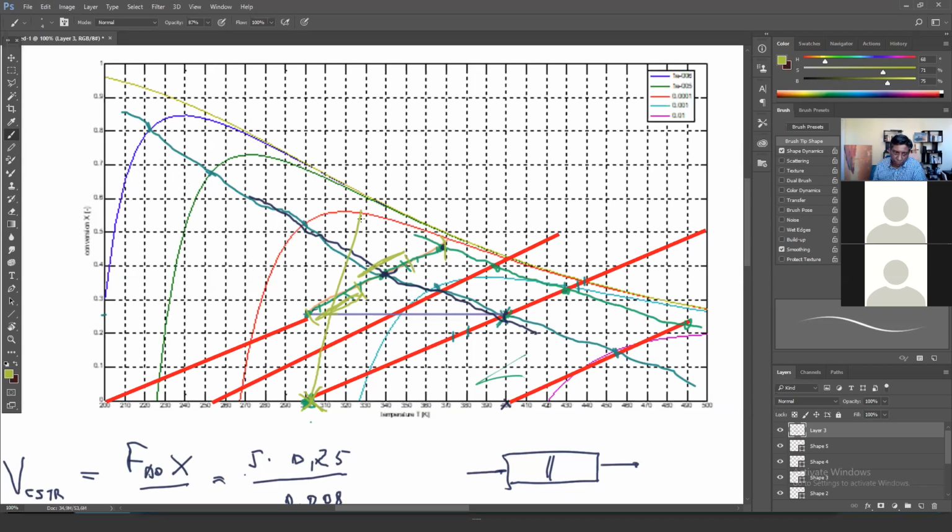So if you do that, then you will be reducing the temperature and also the conversion. You'll be adding reactant to a product. So you'll be pushing your conversion down, but you'll be getting to a high rate region. And you would do that if you have an easy to separate mix, especially if you have, let's say, the reactants in the gas phase and the product in the liquid phase, or the reverse.